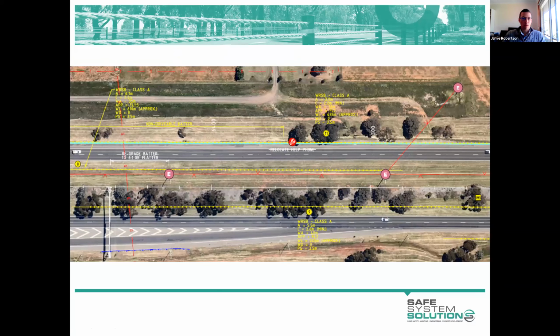I like to show this photo because it demonstrates the old approach to designing barriers. Not that old, we're only talking perhaps 10 years, if that. At that time, the preference was to locate barriers as far from the road as possible. We were designing those barriers based on clear zone thinking, which meant that we could minimise the amount of barrier that we needed to install.